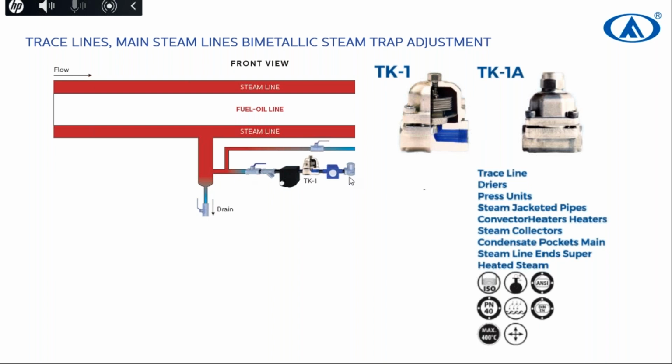Should the indicator be installed before or after? Flow indicators can be installed before or after. It depends on the steam trap type. For float type, before is better. But for example, for thermodynamic type, after the steam trap is better, because in a thermodynamic type you will see it open and close itself 5 times in 1 minute. It's easy to see after the steam trap. For sight glass, I'm talking. But for float type, before the steam trap is better to use.